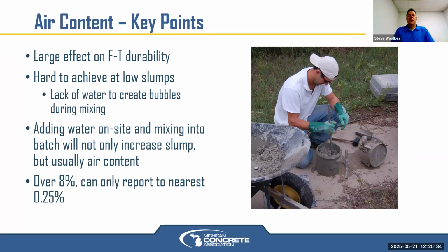Also know that if you start getting up above 8%, typical MDOT specs for full pay are 5.5 to 8.5. Historically, they were 5 to 8, or in the old spec books, they were written 6.5 plus or minus 1.5. But just know that there's no such thing as an 8.1 or an 8.2 per the ASTM specification. Everything above 8%, based on the dial that's shown there, is only read to the nearest 1/4%. So that's something else to note and have a discussion with your field techs. It's either 8 or 8.25.